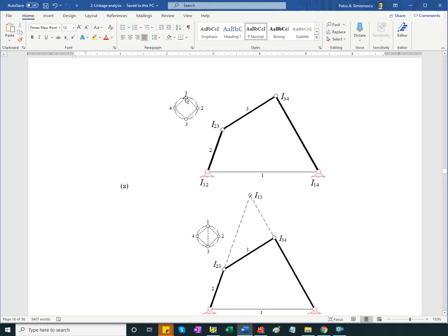You position about equally spaced dots, 1 per body of the mechanism that you are analyzing, and once you find an instance center, you connect the respective bodies. So I have 1, 2. I figure out where it is. I draw the line that connects 1 and 2. Find 2, 3. Draw the line between 2 and 3. 3, 4, and 1, 4.